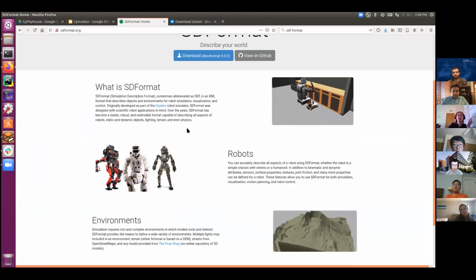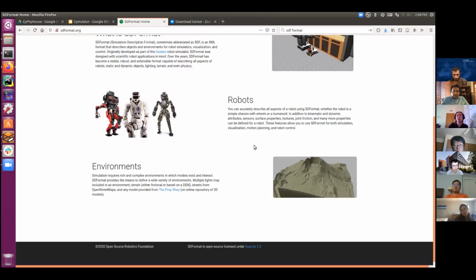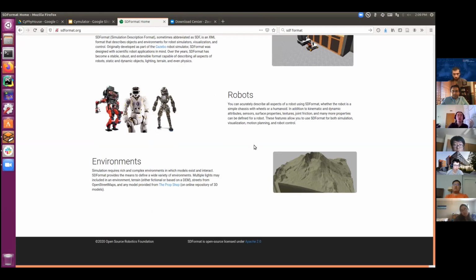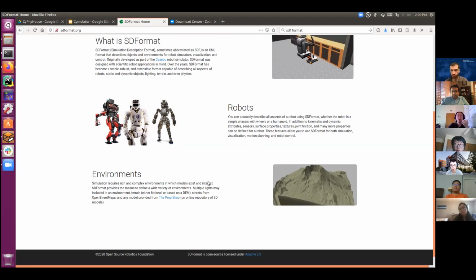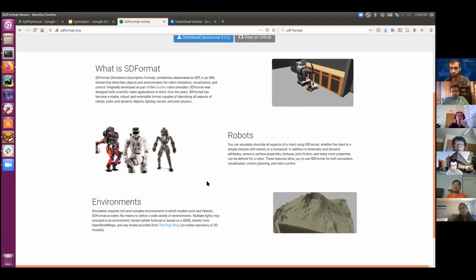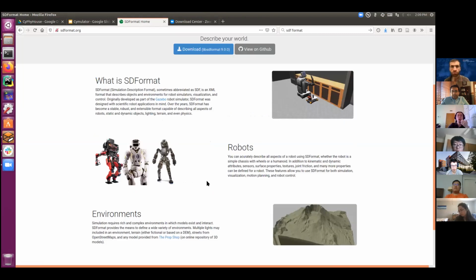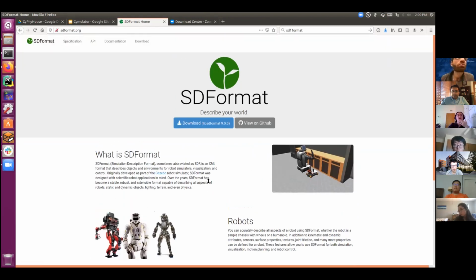I think they have something on the AutoCAD side, a tool to export an AutoCAD model into SDF format, but it's still very specific to Gazebo. This is what Chris was also talking about the other day: if you're using other 3D modeling tools like Unity, it seems there's a way to go at least back from Unity to SDF. So there exist some translators.